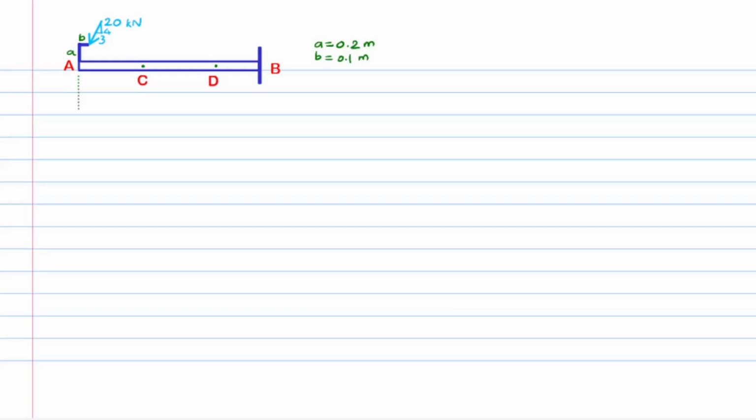Important key points of loads on the beam are marked and labeled as C and D. We now mark the given lengths of the parts of the beam. Additionally, we place a uniformly distributed load of ordinate 20 kN per meter between the part CD. Also, a uniformly varying load of ordinate 0 kN per meter at C and 30 kN per meter at D is placed on top of the uniformly distributed load, so that the total load at point D reads 50 kN per meter.